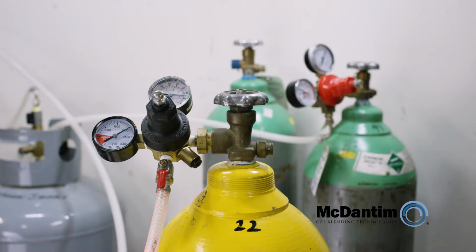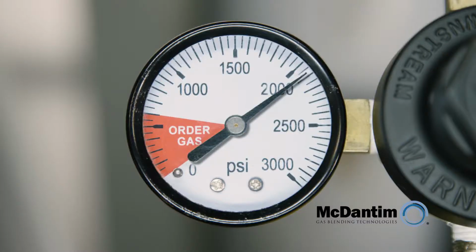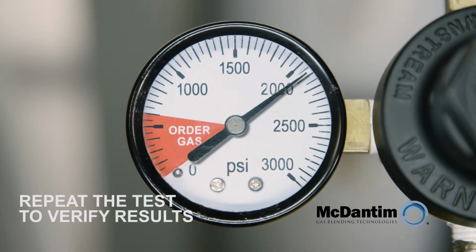In other words, you have just leak checked every fitting from the nitrogen cylinder to the outlet ball valve on the blender. Leak intensity can be gauged by how quickly the nitrogen gauge needle drops. If there is no drop in pressure after about a minute, this indicates no leaking.